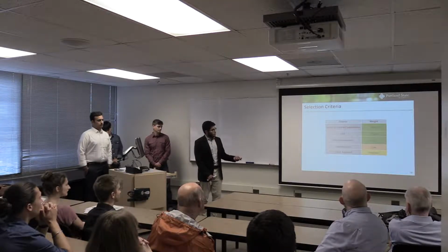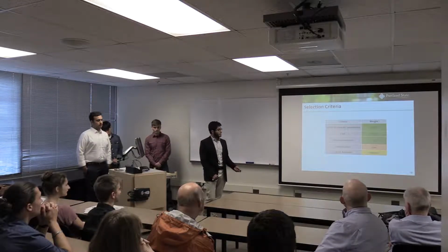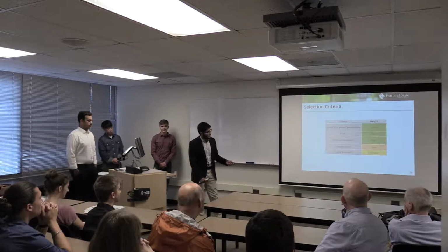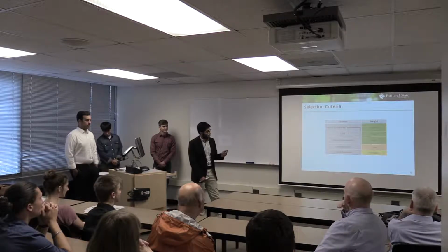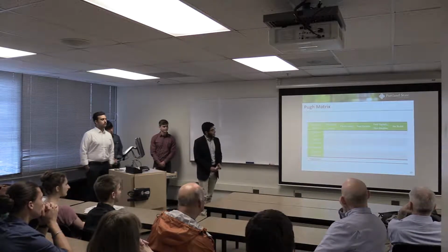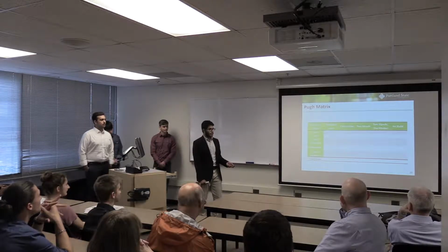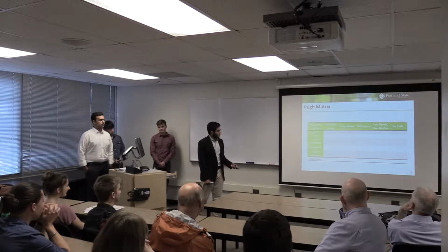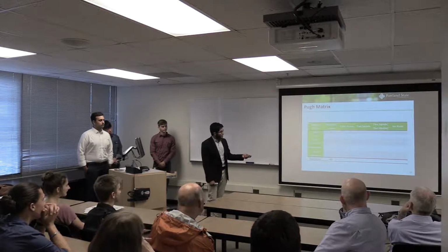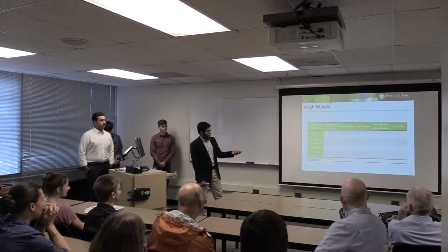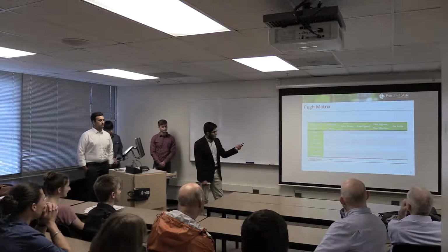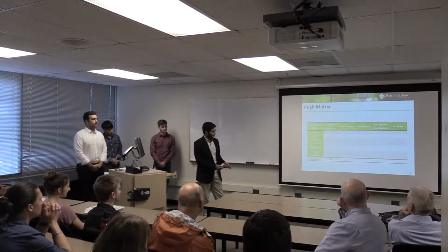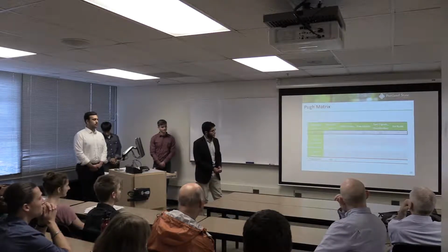These criteria have different weights based on how important they are to our client. So we have safety, cost, and road congestion weighted high. However, maintenance has the lowest weight. We use the Pugh matrix to start the alternative analysis. As you can see here, safety, cost, and ramp have the maximum score, 15 out of 15, and we have maintenance 5, and cyclist approval 10, which gives us a score summation of 60.